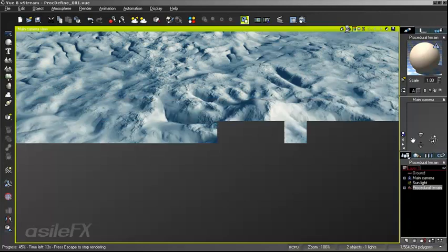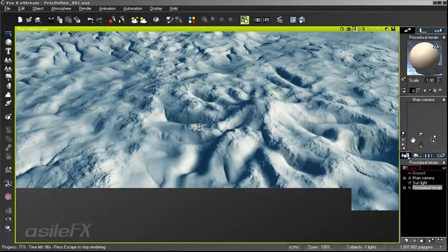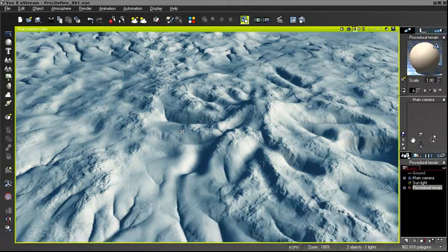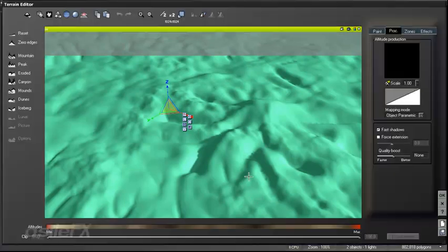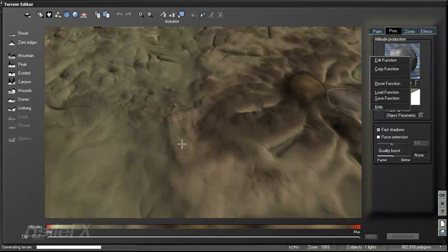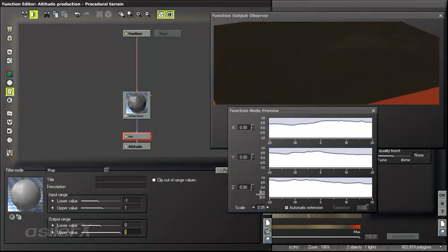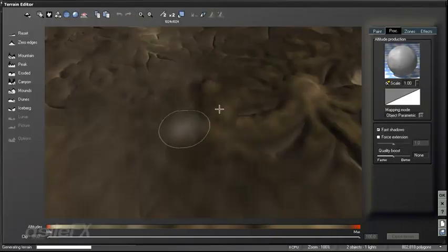But depending on the output that is mixing with the standard terrain level 1 geometry, you may not see much of the fractal because the output may need to be adjusted. So you can use that map filter to limit the output amount to only work within certain values. So let's go ahead and set that map to 0 for the low value and 1 for the high. And we're going to see how that works out.